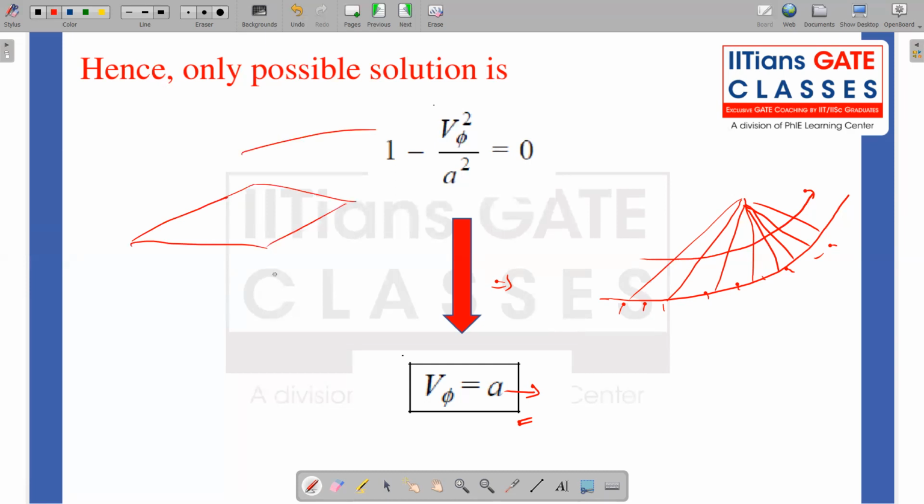So I have a supersonic intake like that. There will be an oblique shock wave, and there will be a very weak normal shock wave, and the compression will happen such that the flow goes through a series of compression corners, so that the fuel can burn at the proper pressure. But in theory, we can design this kind of compression with no total pressure loss, or no entropy change at all.